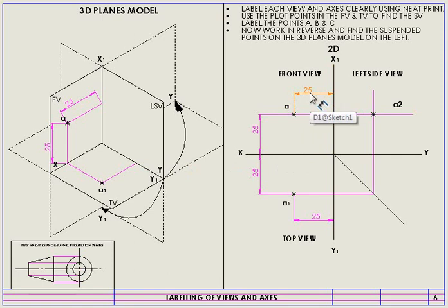So I'm going to take this 25 millimeters and plot it away from this x1, y1 axis over here. Remember, every horizontal line in an orthographic projection will become a 30-degree line. Since I have these lines that I can draw parallel lines to, I can simply draw a parallel line 30 degrees in this direction at 25 millimeters.